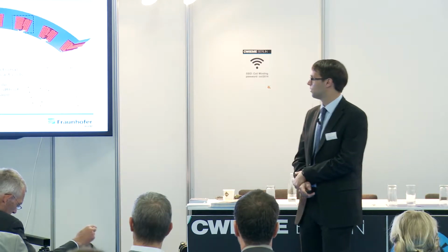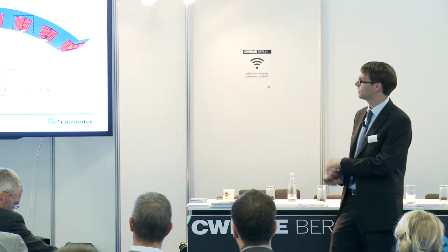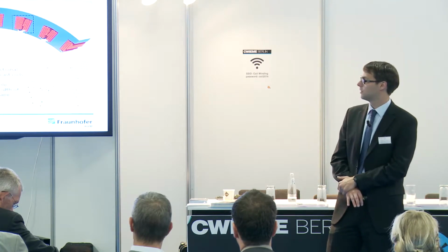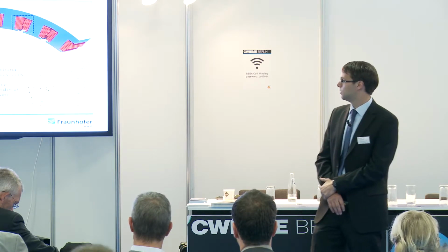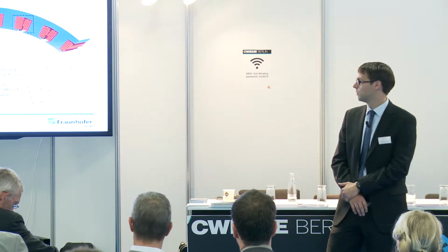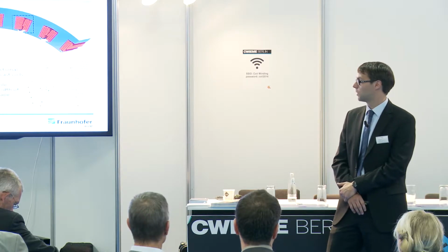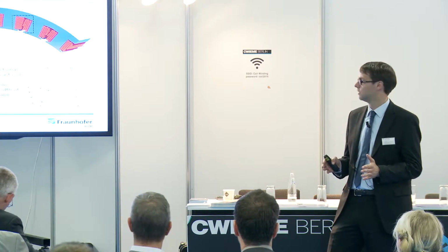So, first of all, the geometrical advantages. By the casting process, we have the possibility of the precise reproduction of the constructed geometry. So we can construct the coil and can realize in every conductor every cross-sectional geometry that we want. And we can use this to increase the slot filling factor. We can realize slot filling factor of up to 90%. And additionally, we do not require a bending radius at the end windings, so we get a very short machine.